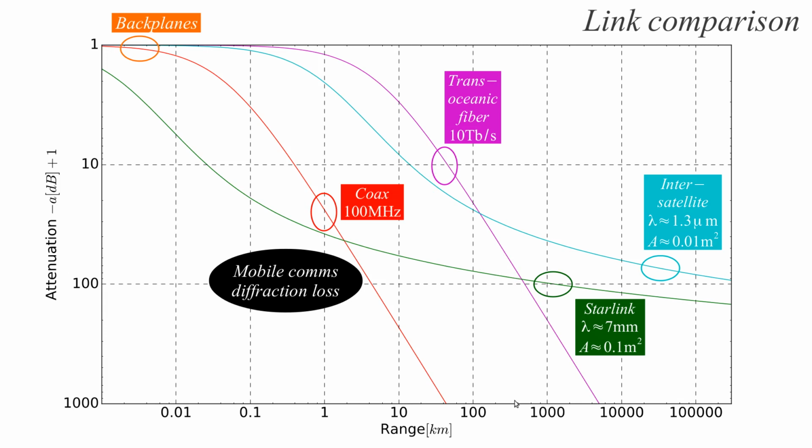repeaterless links up to 300 kilometers, where we don't want to have repeaters, just not to have anything under water. We have to reach an island 300 kilometers from shore. We can still do it without repeaters with an optical fiber. But definitely guided waveguides are not suitable for very long communications. Forget deep space here. Deep space, only radio communication and laser communication can go into deep space.